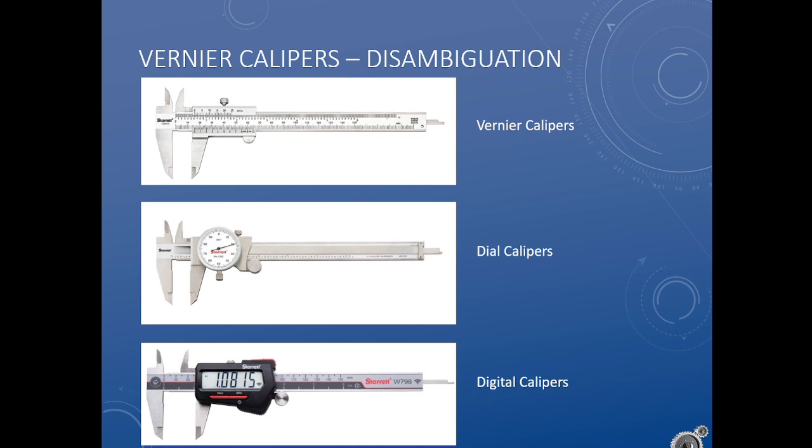They're much more delicate. You drop them, you've ruined them. I have dropped these many times. So these are more robust, certainly, than dial calipers and digital calipers. It's basically the benefit of them. The reason I'm forcing you all to use vernier calipers this term is, well, we'll come to that. But the big one is they're very cheap. You can't get a $5 set of digital calipers that I'm aware of.